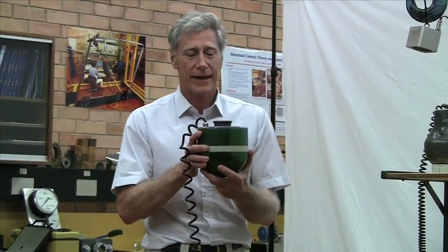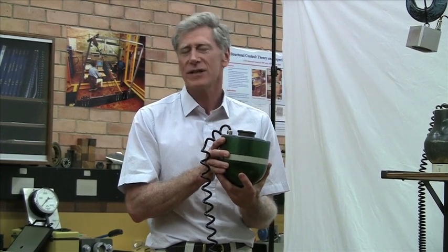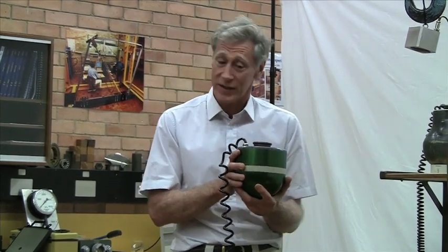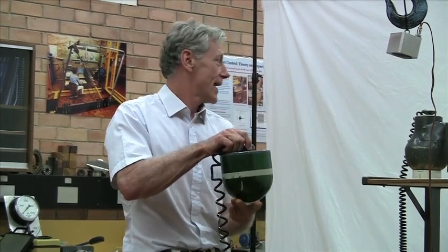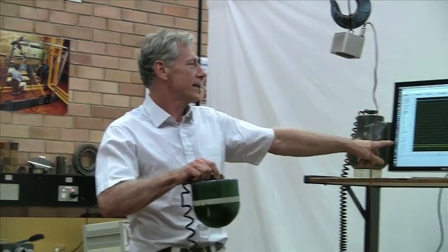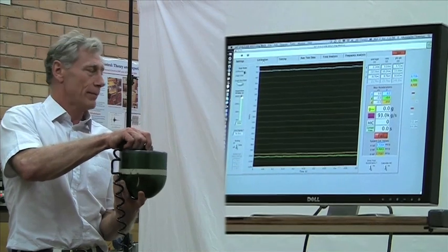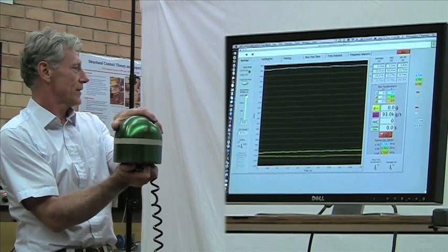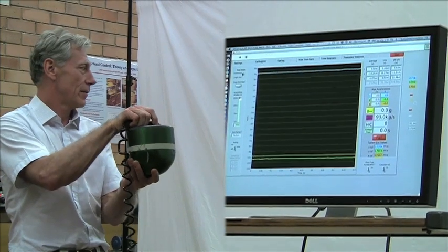Before we use the system, we do some calibration and we just make sure it's working. And one of the simple things that we do is we do what's called a 1G inversion. And if you look at the screen here, the Z is the orange sample, and if I turn this over, you can see that line moves.